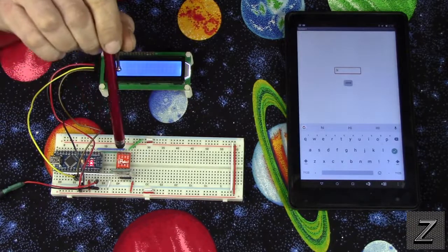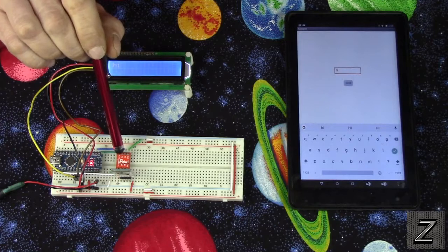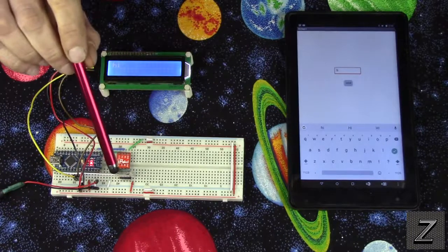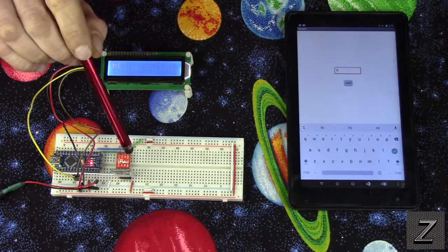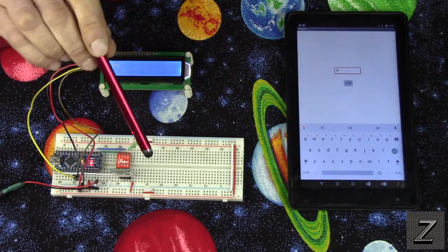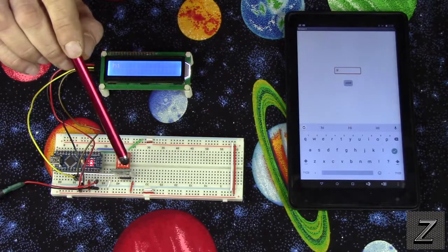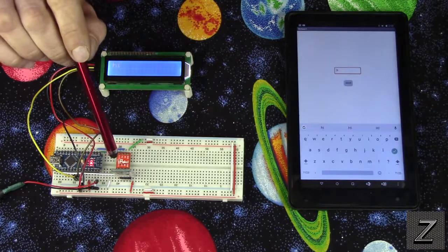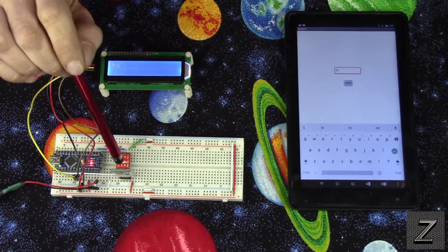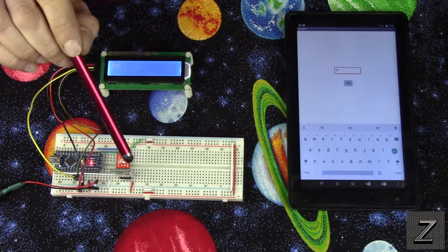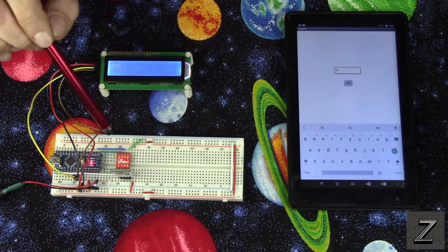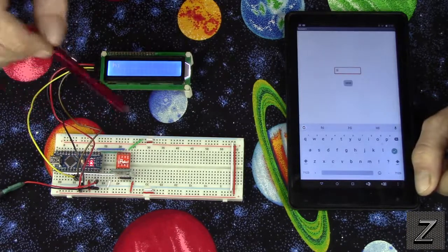And this little logic level converter is like $1 if you only order one. And if you order multiples, you're going to get them even cheaper. This is just a 2-channel, which works perfect with the HC06 or 05s. You can get these in 8-channel, 16-channel, if you're using multiple devices that use the 3.3 volt logic, and they're cheap. I recommend using these over the voltage dividers. It just works better, all the way around. So that's all there is to it.